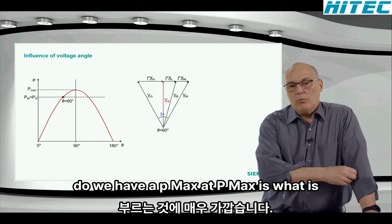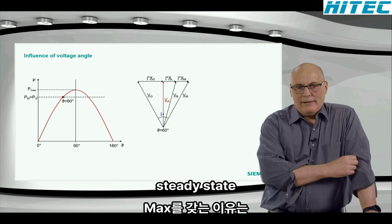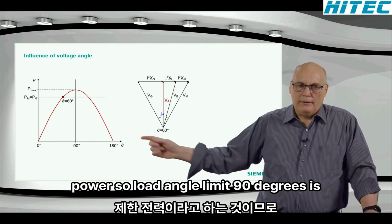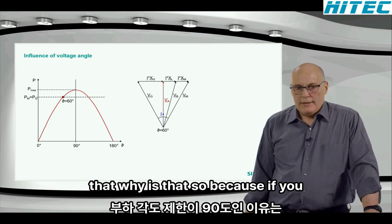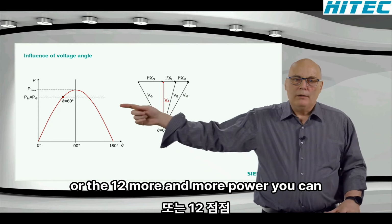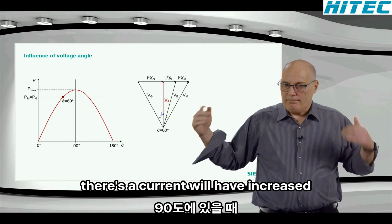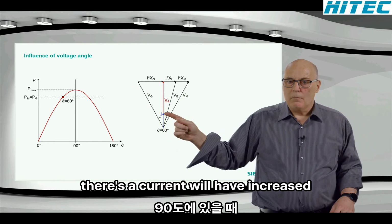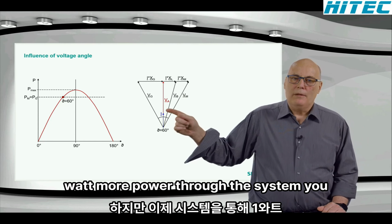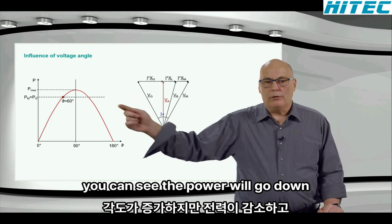The Pmax is what is referred to as the theoretical steady state power limit, or load angle limit, at 90 degrees. Why is that so? If you imagine that the load and the generation want to transfer more and more power, the angle will shift towards 90 degrees, and when you're at 90 degrees the current will have increased. But if you now want to put even 1 watt more power through the system, you will try to increase the current. What will happen? The angle will increase, but the power will go down.